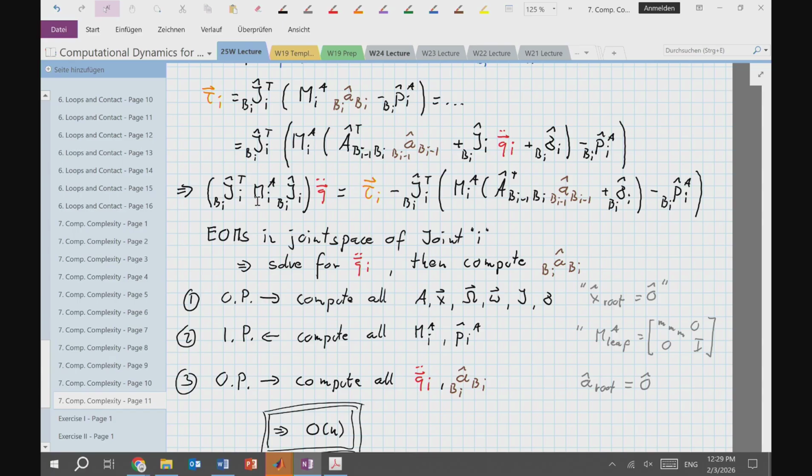But if you think about this, in your controller you can compute this guy, right? And then have adaptive gains that make sure that your joint controller optimally reacts with some phase reserve, all the quantities that you want to be as quick as possible without getting unstable. And this will tell you what the mass is that is involved. For a rotational joint, that's a scalar quantity that depends only on Q. So if you know all your joint angles of the rest, you know how heavy this thing is.